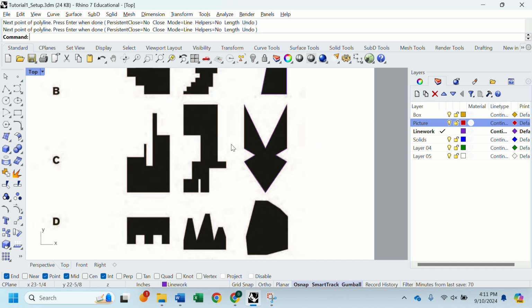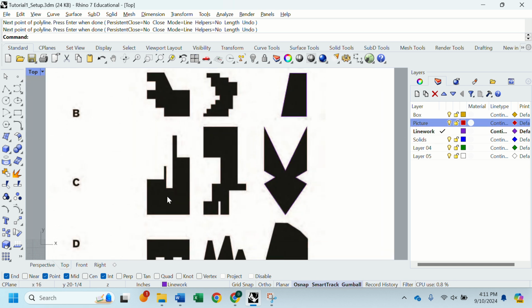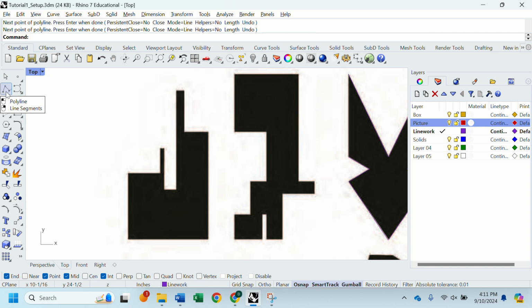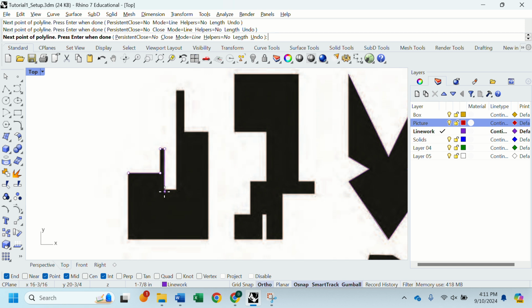All right. We could draw it as a series of lines. So another technique would be to do this object here, okay? If we were to draw maybe part of it, let's go here. I'm just going to hold my shift key down so I can maintain my orthographic lines here, keeping them orthogonal.